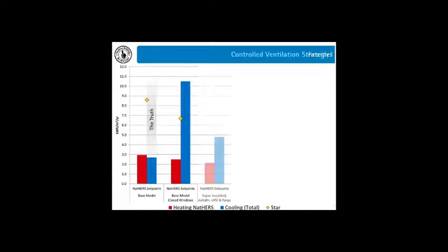The next step is then, well, what happens when we super insulate that structure? We take into consideration air tightness, we take into consideration thermal bridging, we use mechanical systems to keep the indoor air healthy, but also to purge heat out in summer. Then we get an outcome that looks more like the last scenario. And that will then bring the star rating back up to 8.2 stars.